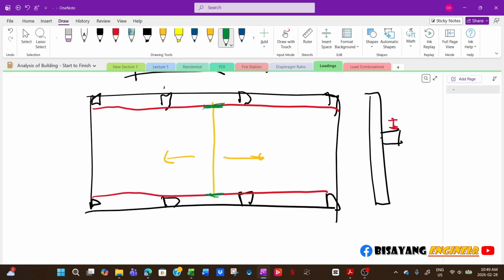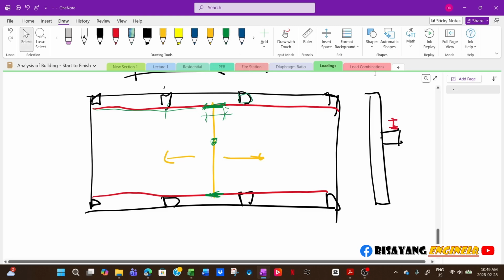So there's an end truck, and what I will do is a mock-up calculation of this, and then I will determine the possible spacing of the wheels for the end truck based on the capacity. That's what I use to design this runway, applying that load as a moving load. And then I will get the maximum reaction. And when I design this particular one, then I will apply the load from the crane.